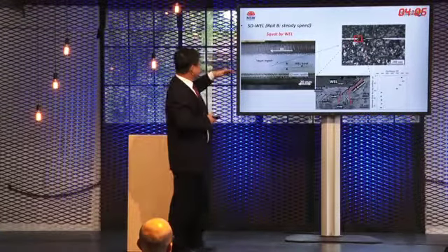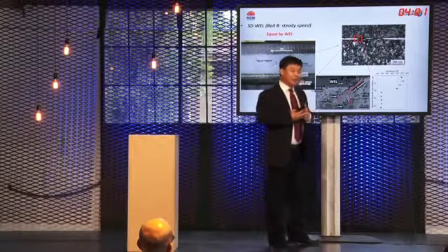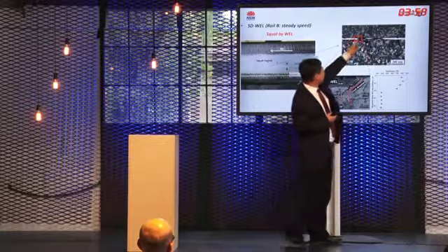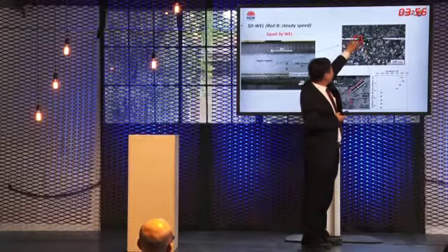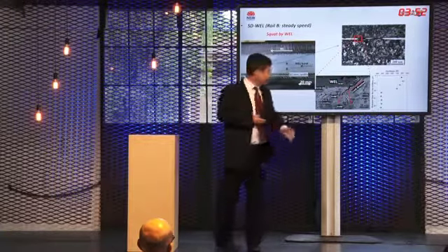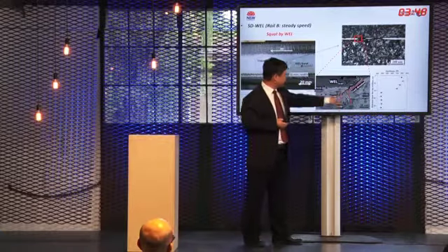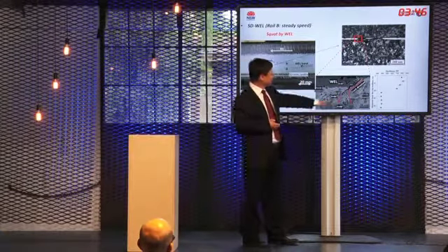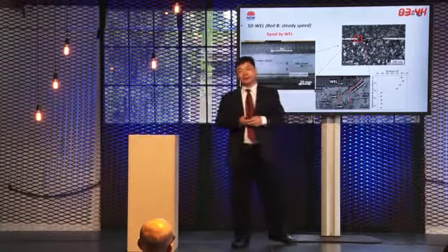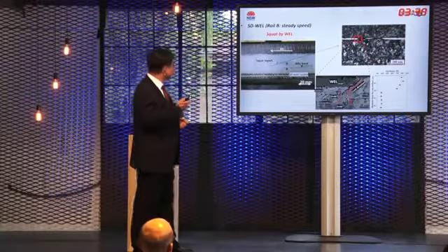Okay, for another region, steady traffic. You see the crack will be different. This time, the crack normally generates from the tip of the tail of the white etching layer. And then, you see here, it propagates going down into the parent material. This time it follows the texture, normally between the grain boundaries.